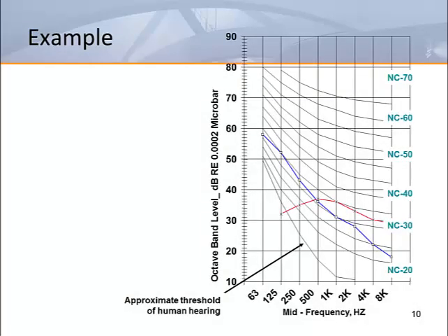This example illustrates one of the shortcomings of using the NC rating method. If we stood in a hallway and measured the room sound pressure near a sidewall grill, it would look like the red plot. We would say it's NC 35 and the critical band is in the 1000 Hz or 5th octave band. This is very typical for grills and diffusers.